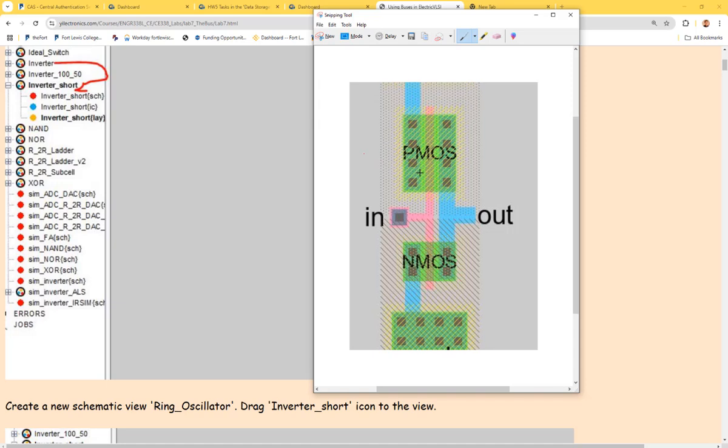I'm having my metal 1 go through like this. Yeah, blue's metal 1. But if I don't have metal 1 here, just a transistor. So what I want to say is, you're not supposed to do that, because these are vias, right? So these vias are what? Via 1.